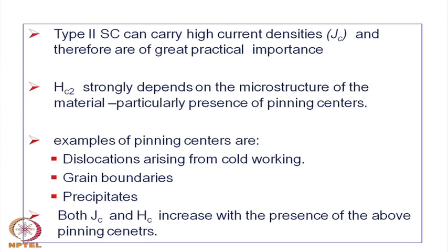So, it becomes difficult for the flux lines to penetrate through the boundaries. Therefore, if you have more and more grain boundaries, the penetration is difficult. So, the Hc2 value can be extended further. In addition,